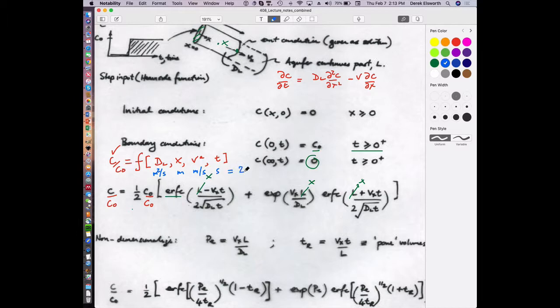So there are two groups. We don't have mass involved in here. Certainly mass is included here, but there's not mass included there. So in terms of pi groups, we have 4 parameters minus 2 variables, and we're going to have 2 composite variables that control our behavior.